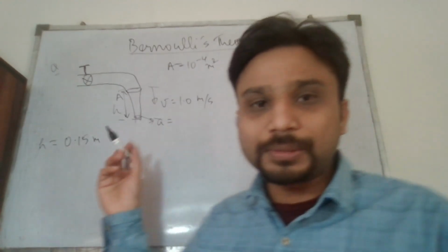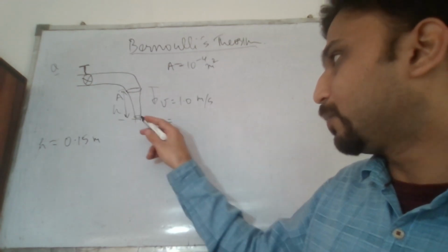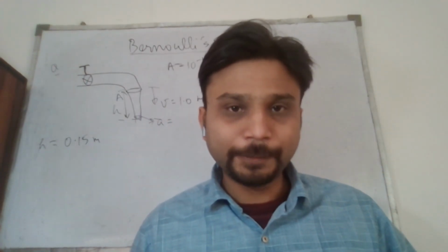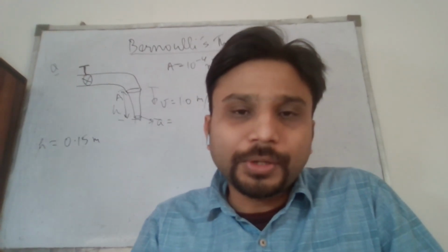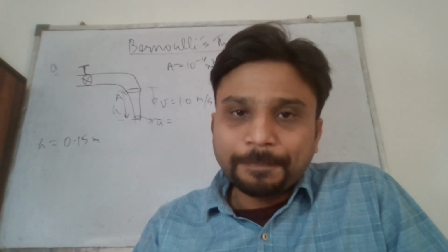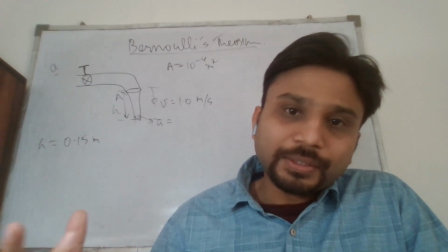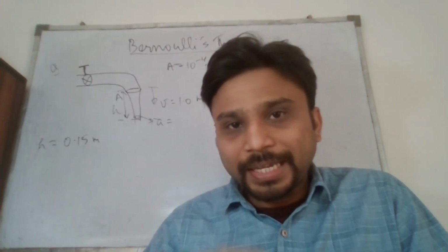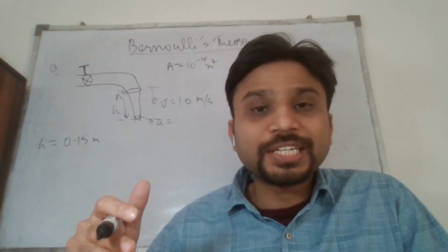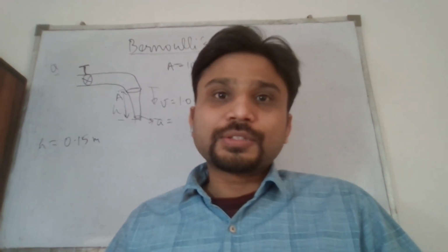This is what you have observed also, right? You would have observed how the flow narrows down and the flow is steady. So, what would this narrowed cross section be? The reason is very simple, because of the equation of continuity. We know that because of Bernoulli's theorem, the speed is going to increase. So when the speed increases, automatically, as per the equation of continuity, the cross-section area has to go down, because cross-section area into speed is a constant. So this is our story.